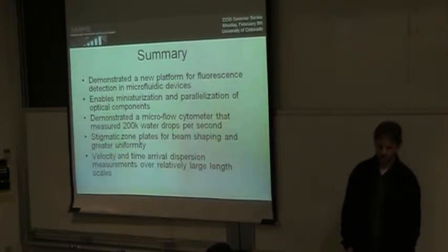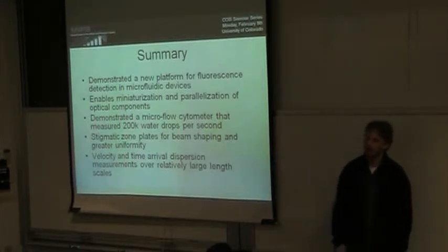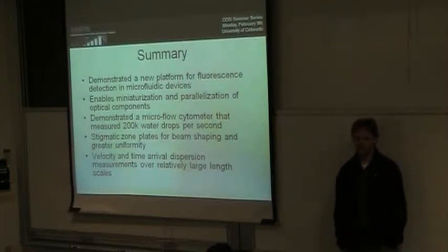Can you talk about replicating these zone plates that have 300 nanometer wide but 600 nanometer deep trenches? Is it hard to replicate them and pull it out such that that feature is reproduced? Yeah, so 2 to 1 starts getting hard. We weren't actually able to make 600 nanometers, which gives us pi. We can do 2/3 of pi, which is 400 nanometers. But does every ring come out? Every ring comes out.